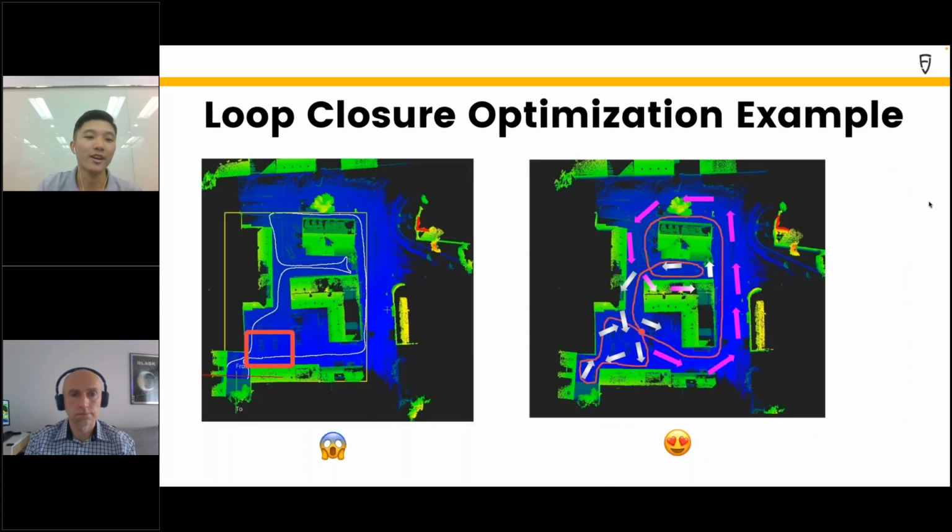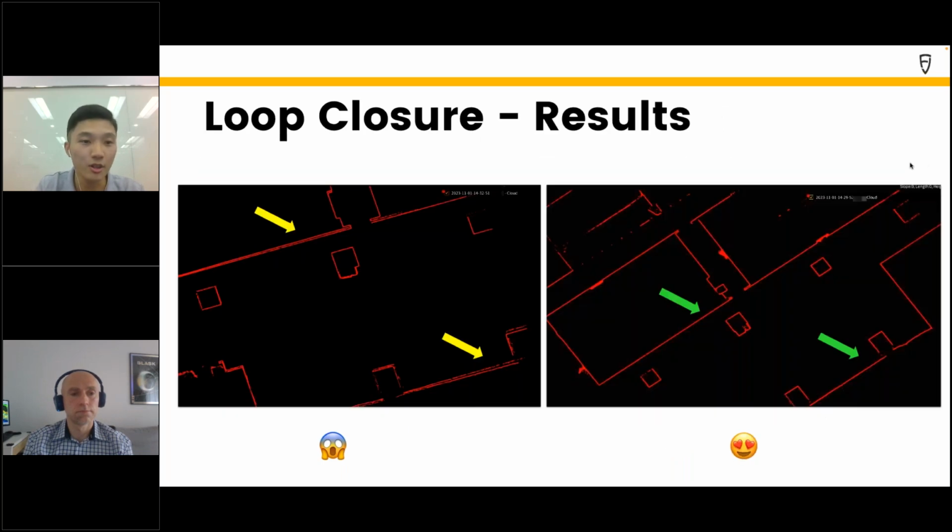So here's a screenshot of what might happen. You can see on the screen on the left-hand side is a less ideal walking trajectory that results in point cloud drift. On the right-hand side, we marked the trajectory with a better way to do the scanning and create a closed loop for this particular space. Starting at the red dot, going from dark pink to a lighter pink at the end, with a white arrow. In this format, it actually has the loop closure. And the result, obviously, you can see on the screen.